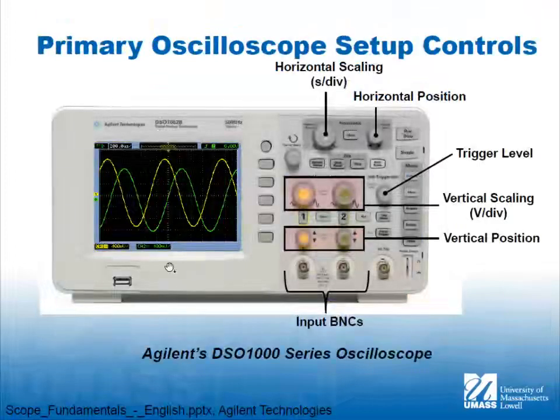So this is what the outside of the box looks like. You've seen these in labs. You've seen them all over the place. You might have used them yourself. This is a fairly simple device. It has 2 channels, so you can display the yellow and the green. We've only been looking at 1 channel. There's the yellow channel, the green channel, a couple connectors that allow you to connect the probes, and an adjustment for the vertical size of the division, so the vertical range here.